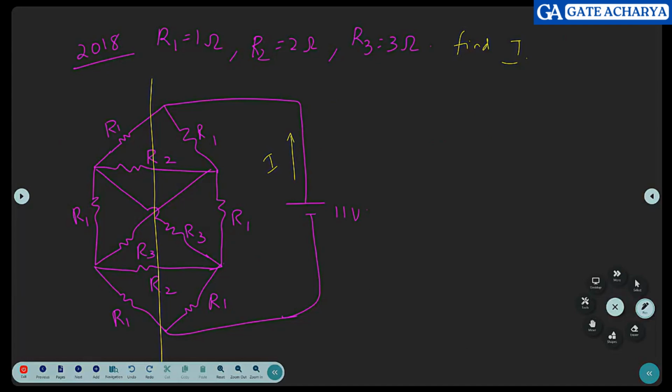Whenever it is a balanced bridge, the voltages here will be same. You take a resistor and connect 100 volt here and the same 100 volt here. I say 1K. What is the current through this? Because current depends on the potential difference. When the voltages are same, what is the current through this? 0. And the potential drop will also be 0. So that means this is nothing but a short circuit. When the voltages are same, this resistor does not matter at all. It's a short circuit. Now you see the circuit will be different.